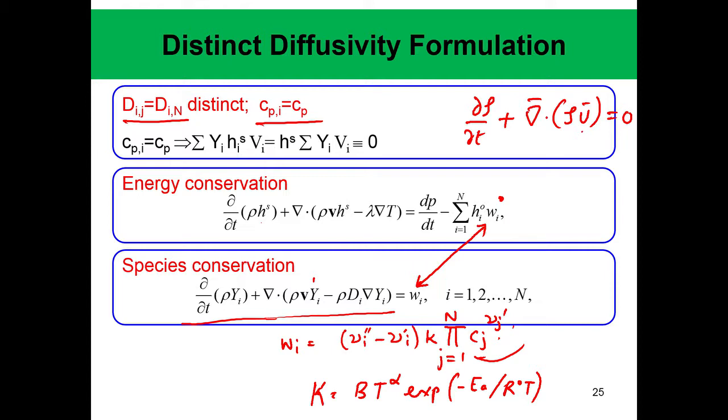It is very important at this stage to understand how the coupling actually takes place through these different sets of equations, because there are plenty of equations involved, but it is important to understand what each term represents and how each equation is coupled to the other equation. If it was not coupled, then life would have been much simpler. We would have solved them separately, but we cannot do that. If you are doing a CFD calculation of a combustor, of a gas turbine engine, you need to solve all of these equations together, okay. And of course you note that this is for the ith species.